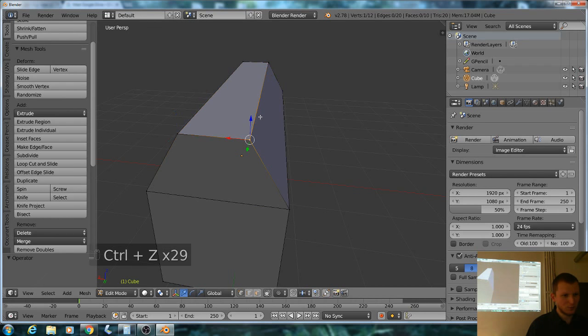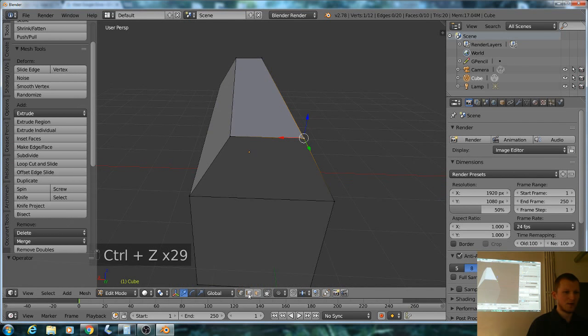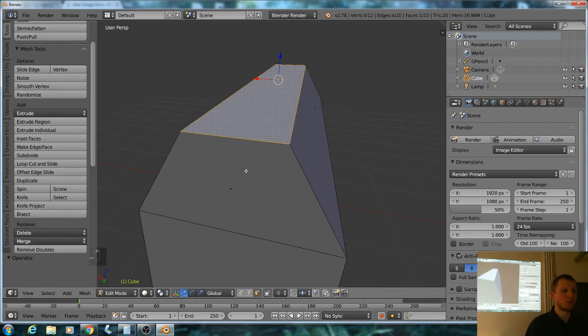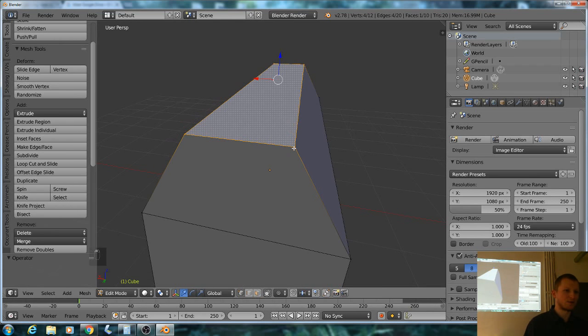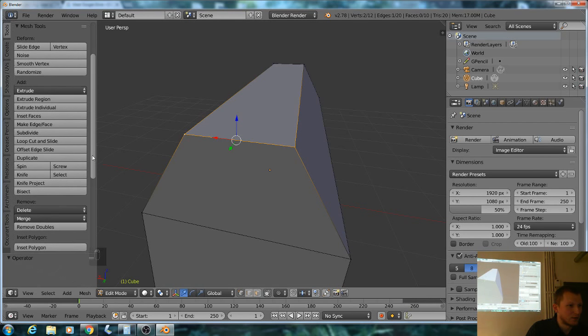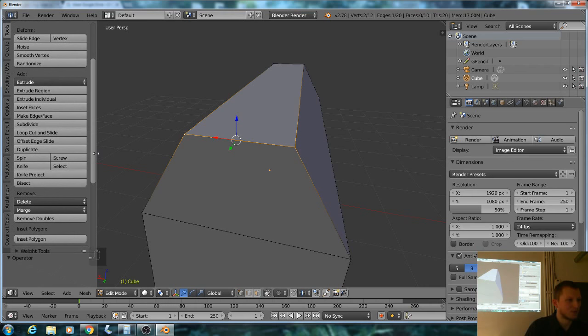But if you did the extrusion and you still have this quad face, then there is another command that merges or joins two vertices. That's basically many operations in one. You either delete a vertex and then join the rest of it, or use one command for just joining them. A little bit down the list, there is this command called merge.